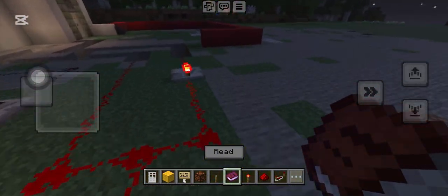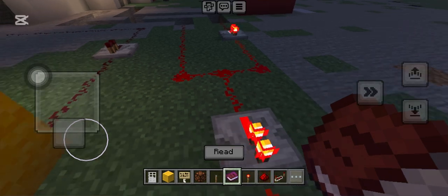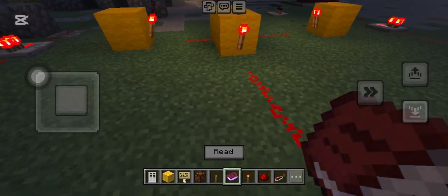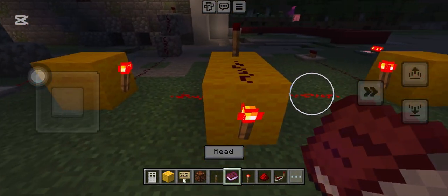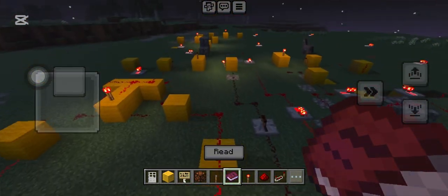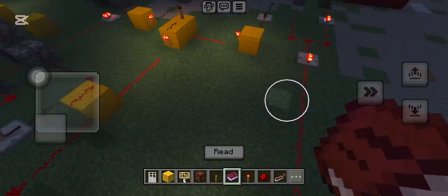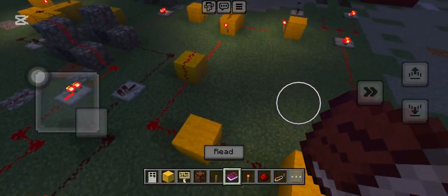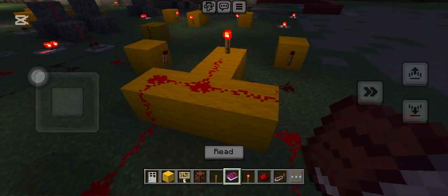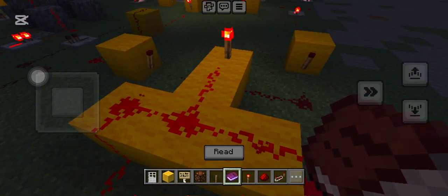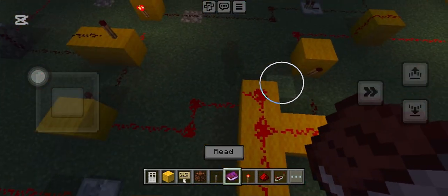Next let's go to our OR gate. It checks if at least one of A2 or B2 is on. The reason we use the OR gate is to build the XOR gate. And this is the inverter, which we use to flip the AND output. Next, let's go to our XOR gate, combined from the OR output plus the NOT AND output. It turns on only when A2 and B2 are different. The output is called the partial sum. This is not the final bit 2 answer yet because it hasn't accounted for anything carried over from bit 1.